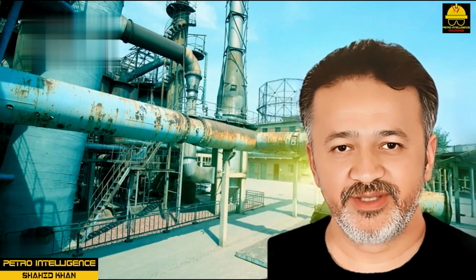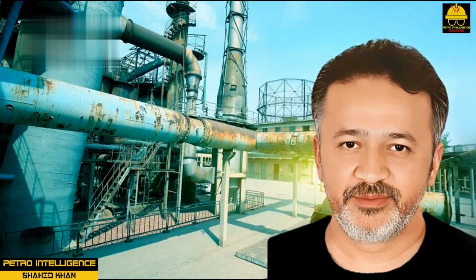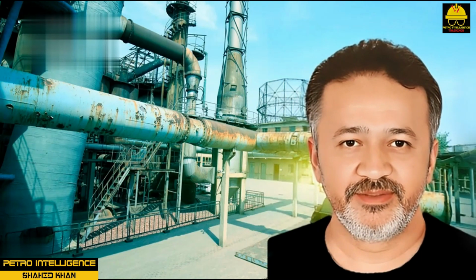The flare burners and piping are designed to handle these flows. They must burn the waste gas with a minimum amount of smoke and must be high enough so that the surrounding area and its equipment are not endangered by flame, heat radiation, and fumes. Flare stacks range in height from 200 to 350 feet. A self-supporting flare stack looks like a large perpendicular pipe, usually with graduated size, and has a burner at the top. Some of the smaller stacks have guy wires for protection against high winds.